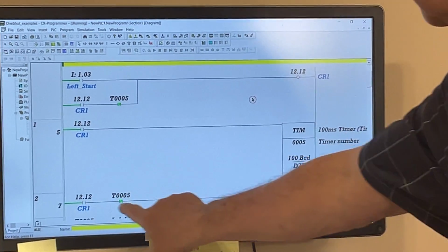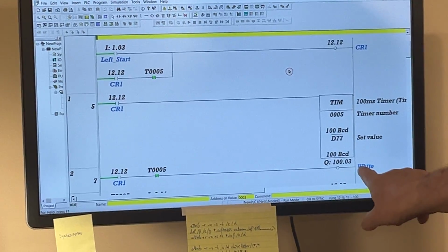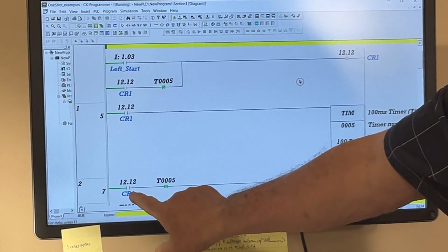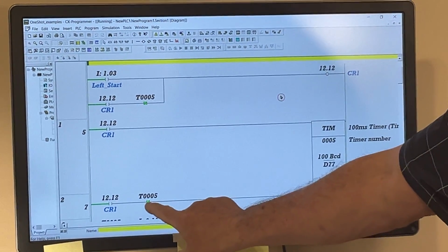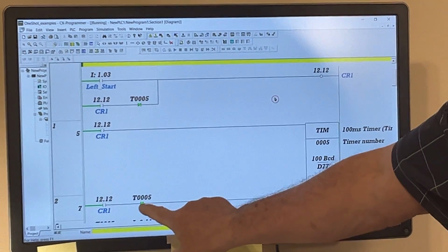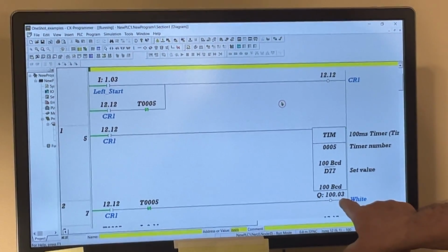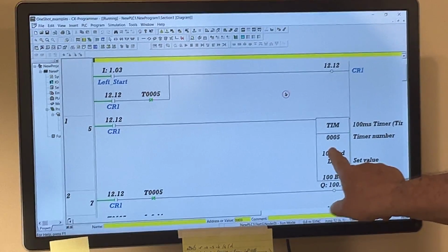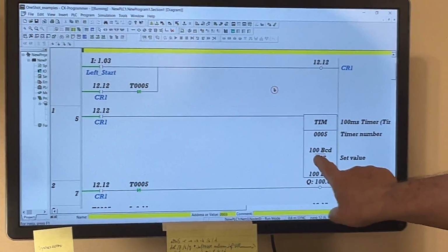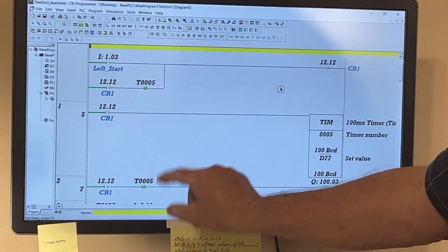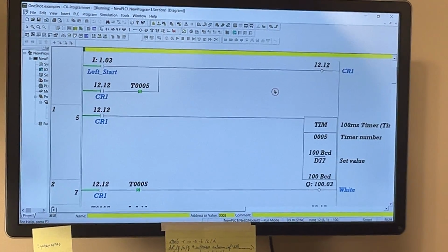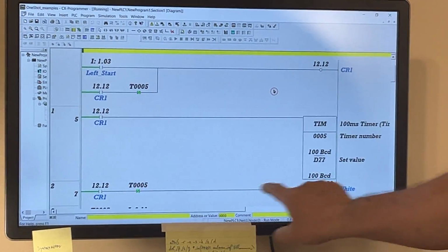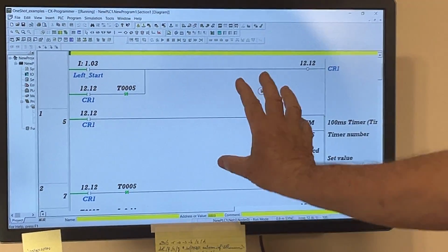And I'm using this last line only to show you the light, because as soon as I energize the coil, this contact here goes on, this one being already on because it's normally on. Okay? I energize the light, which is a white LED, and in the moment the timer finishes counting the 10 seconds, this one goes shortly off, cutting the line, so the light goes off. This is actually the monostable in programming in a PLC.